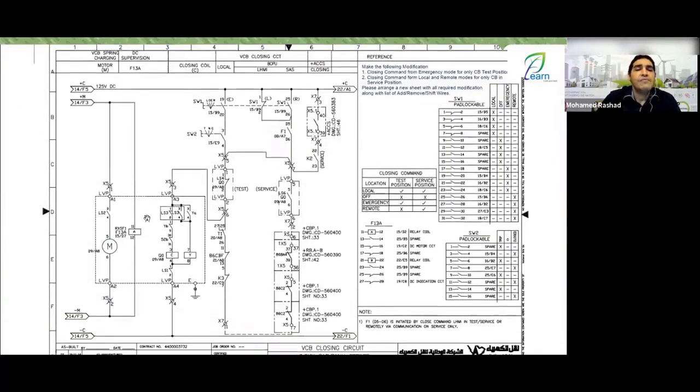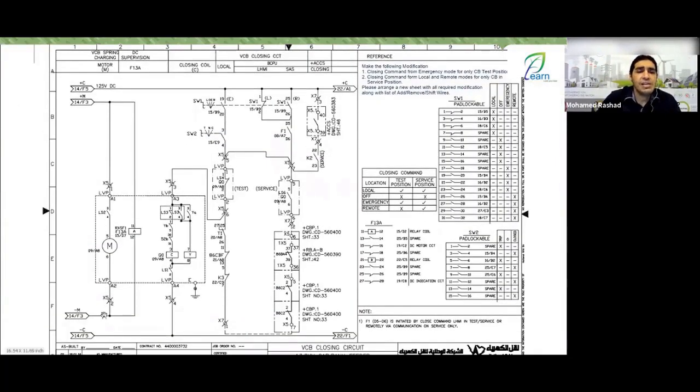All right, very good. So here, what's going to happen is that you brought the supply here and now you want it to go to the motor. Well, the motor, in all the circuits you will see in front of you, the thing you want to operate will have a negative connection and is waiting for the positive to reach it through your control circuits. It has a negative connection and is just waiting for the positive to operate.